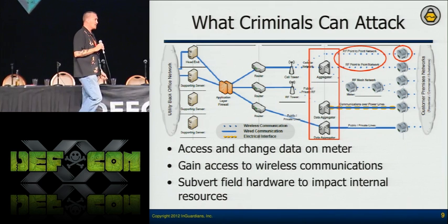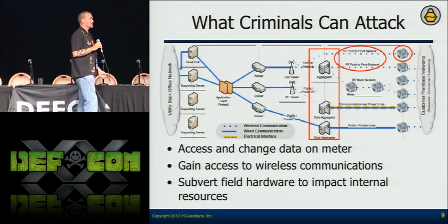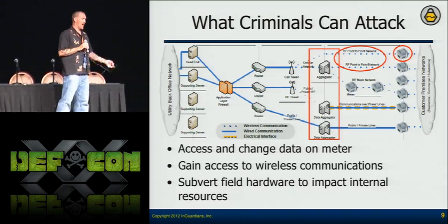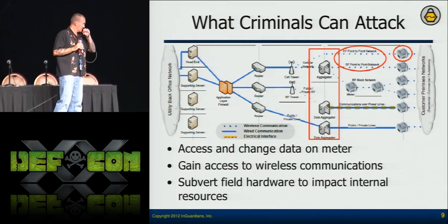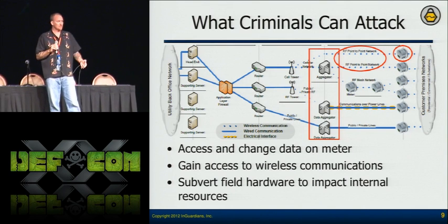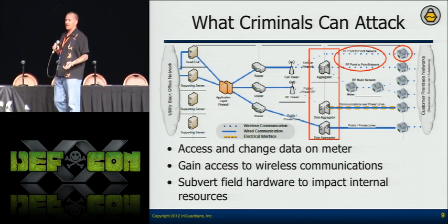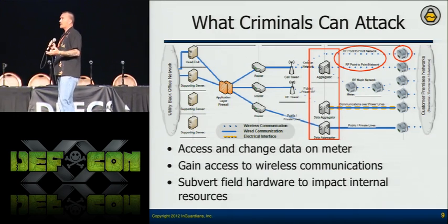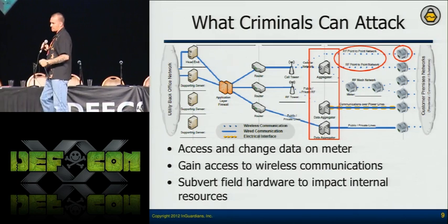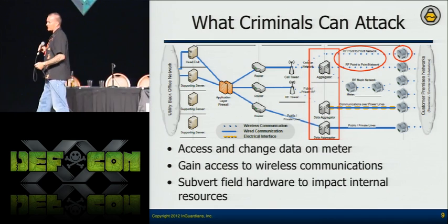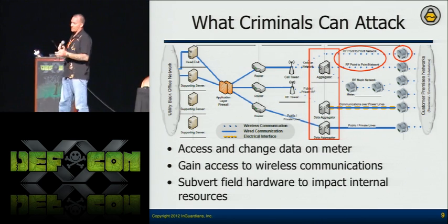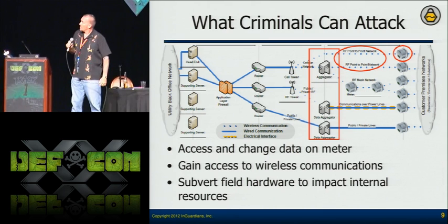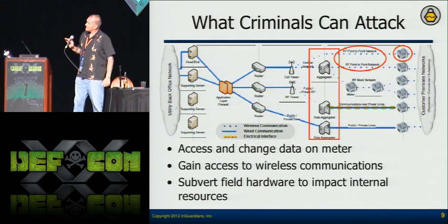They either communicate over 900 megahertz, communicating with other meters and with the aggregators that are on the pole top, or they've got network interface cards that have cellular modems in there, so 2.4 gigahertz. And those won't need an aggregator except for in remote locations, and those will just talk back directly to the cell tower. But we're concerned with all of those things in the red.